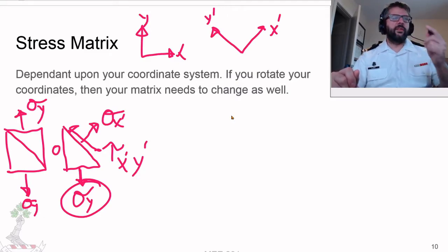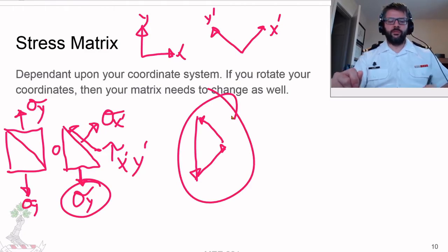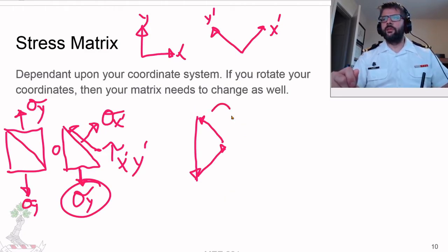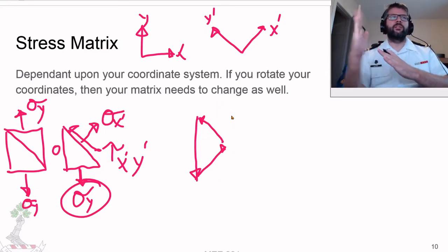and the other thing that we know is, if we've got this one downward force, and we've got this force acting at 45 degrees, and this other force also acting at 45 degrees, these two forces need to be the same in magnitude, because they're both acting at the same angle.